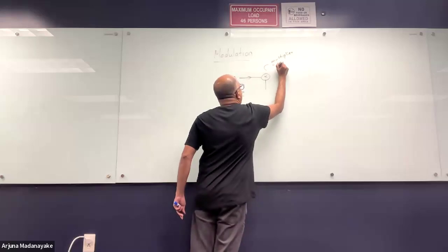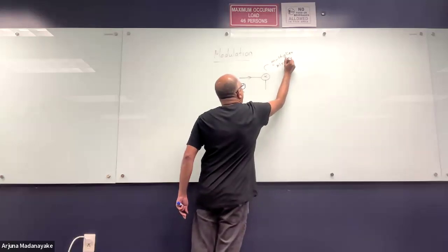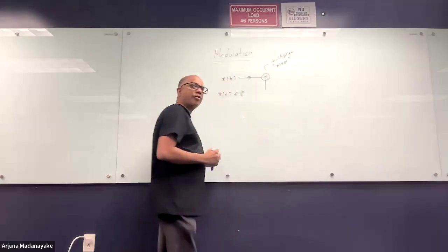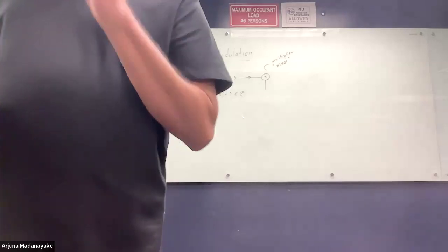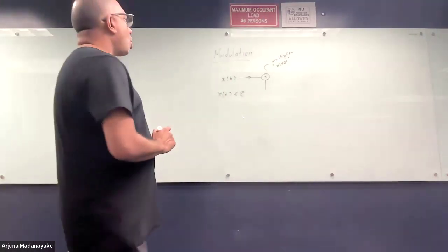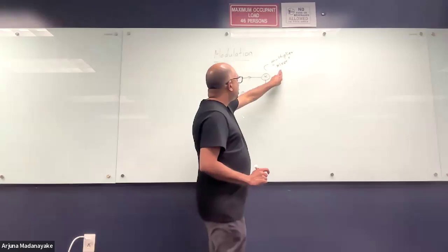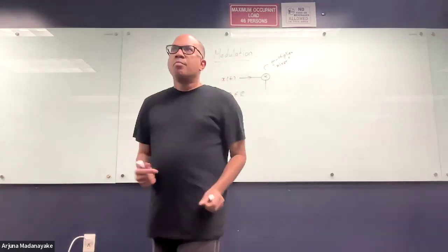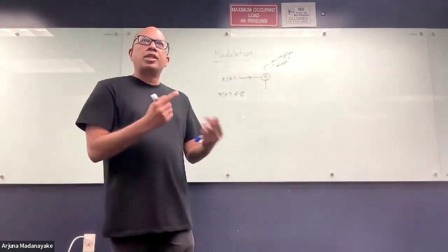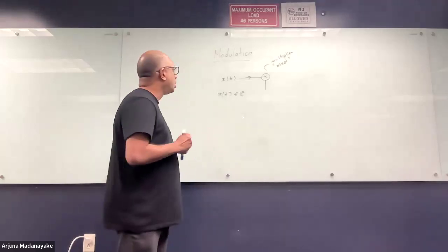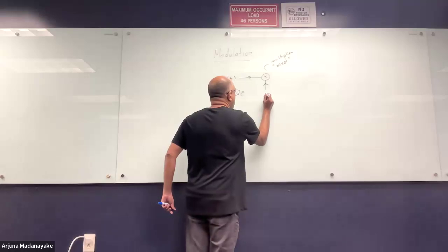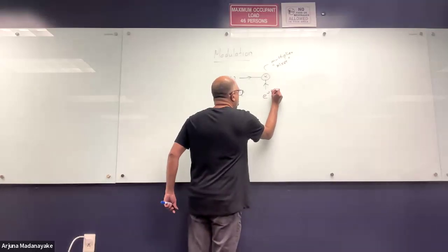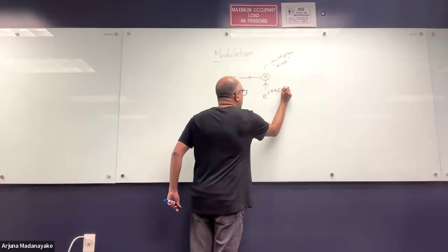You can always call it some other stuff, we can call it a mixer. If you look at a radio frequency design book, the mathematical operation is multiplication, so it's called a multiplier, but in the jargon, people call it mixers because it mixes your complex exponential signal with the waveform. And from here, we send in our complex exponential waveform, e to the j 2 pi f0 t.